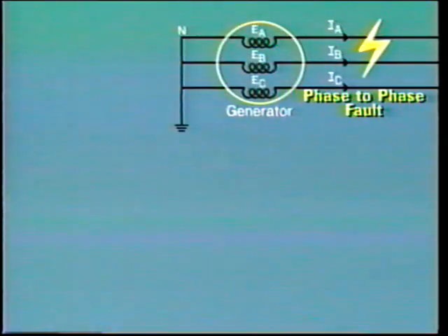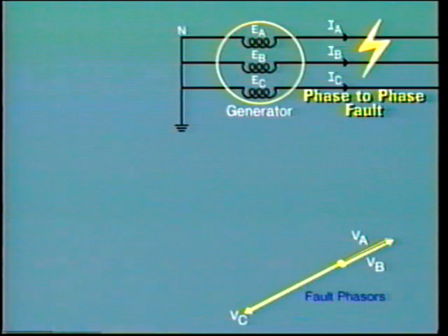Now, when the fault is unbalanced, say a phase-to-phase short circuit, it is not so easy to analyze. For study purposes, the short circuit is considered to have zero impedance. This phasor diagram shows just how unbalanced the system becomes under these conditions. Due to the unbalance and change in impedance, the voltages on lines A and B have come together because of the short circuit.